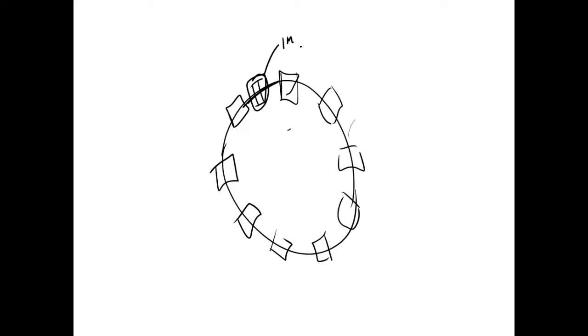So most of them run what they call a dual channel Token Ring. So you have a backup channel. You have one channel going, and the other one rotates in the other direction. It's really neat. And if you have an open, it'll automatically switch you over to the other one and send you back in the opposite direction, if it can't get all clear.